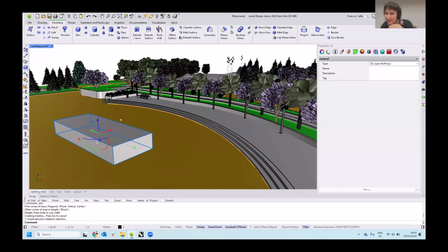When you have a Rhino geometry, you go to the properties, there is this IFC tag, and you can assign a specific IFC type to that object. So we can, I don't know, export this as a ramp, if you like, or as any other type that is listed here, which corresponds to product types.